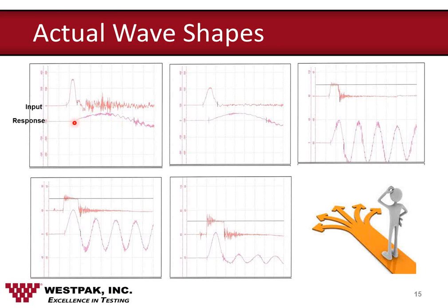You can also see that the response is out of phase with the input. In other words, the response doesn't start until the input is nearly over. So that defines a system that is responding to the velocity change of the input, in other words, the area under this acceleration versus time pulse, rather than to its peak, because this peak is very much higher than this peak.